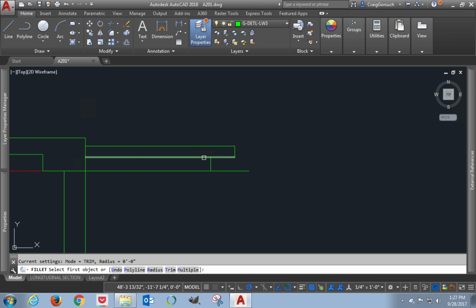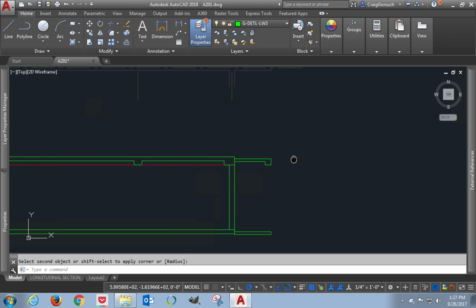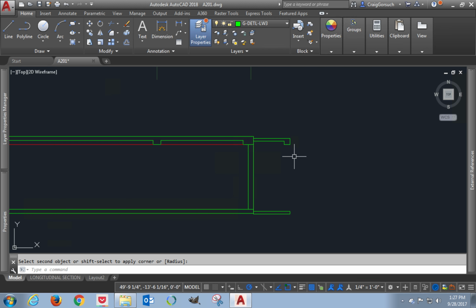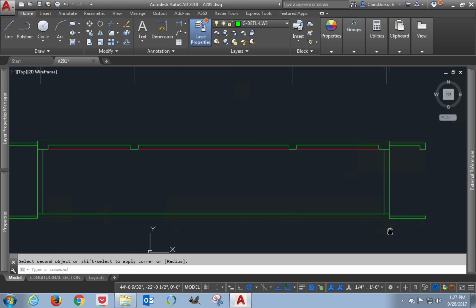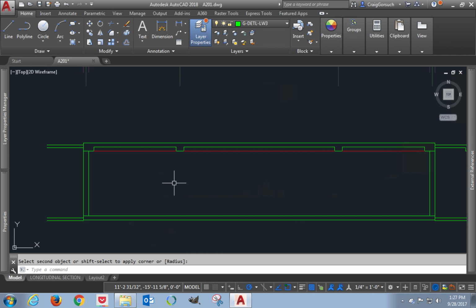and I'm going to use my fillet command to clean up this intersection and put that beam there. There'll always be some sort of thickened slab. There's always going to be a reinforcing of the corner of the slab at a suspended balcony like that. Down here at the ground level, it's just going to sit on dirt. So we're in pretty good shape. There might be a thickened edge, there might not be. We're not going to worry about showing that right now.